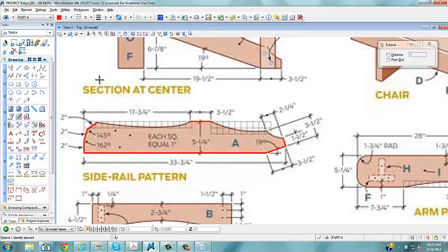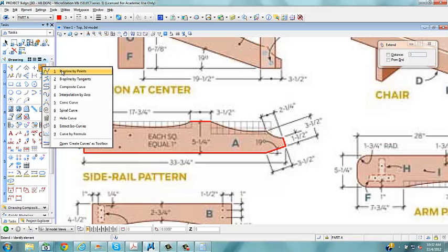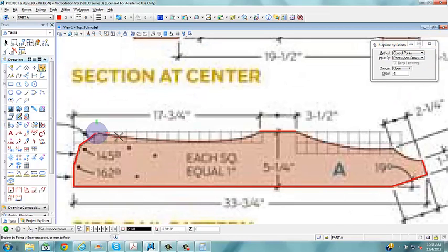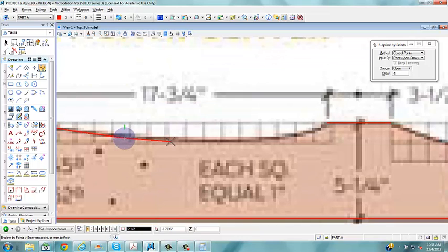So now we've got these other lines, and what we'll use is our Bezier curve lines. We can use our B-spline curve. We'll kind of zoom in on this, and what we want to do is kind of snap and just follow this contour as best we can. If I hit Q, I can get out of the AccuDraw, so it gives me a little bit more control. And then when it snaps up here, I'll just left click and then right click. So it gives me that nice smooth line.